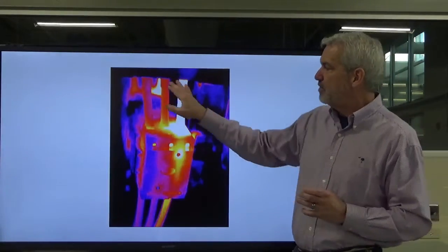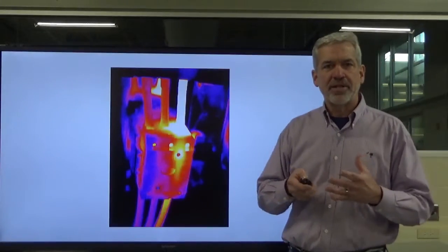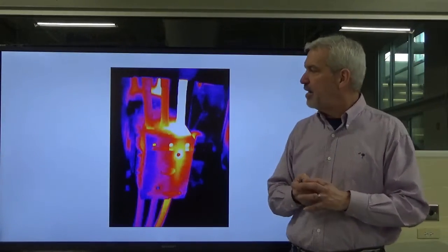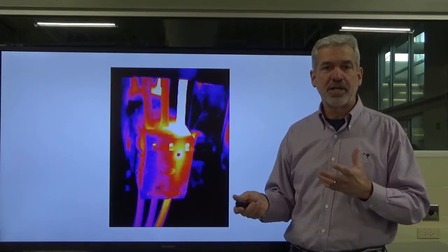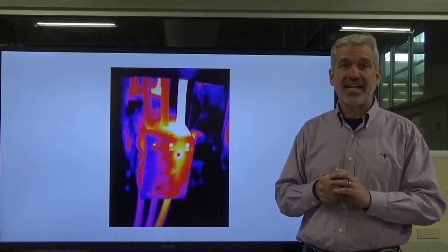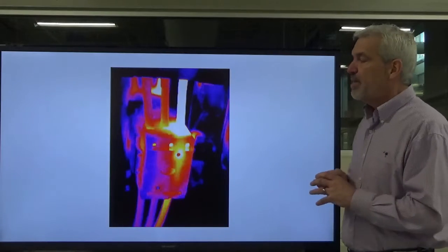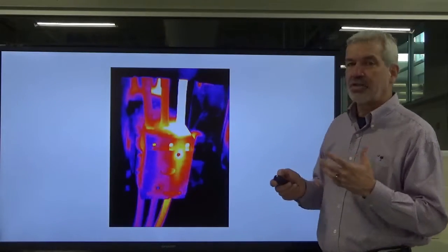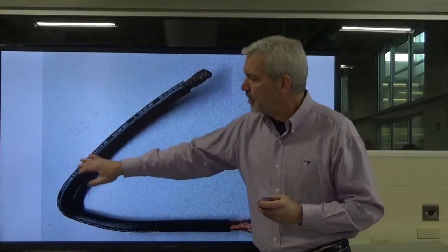So we were able to look at that. They didn't need the camera, but it was just something I thought I would bring down there to scan the entire cabinet. And as a result, we found some loose connections, so we fixed those very quickly. And follow-up action is going to be, we're going to do some preventive maintenance in that cabinet, tighten some terminals, look at some connections and things like that. But my point is that we used that thermography camera.